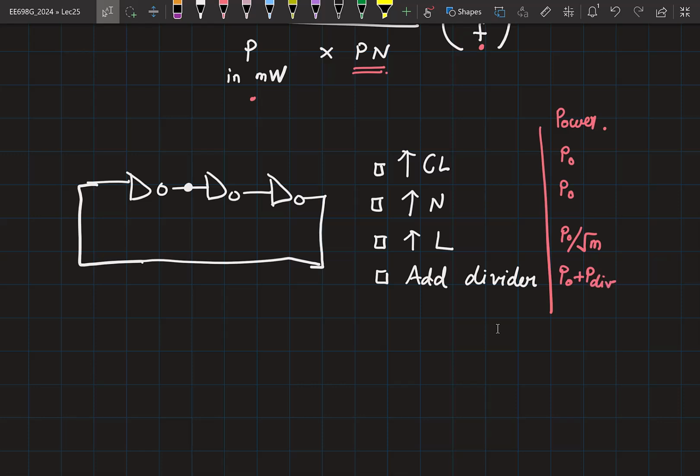Right? And now we have started comparing them based on the FOM. What did we find when you increase CL? What happens? You are adding additional capacitance, so you have both the expressions here. How do both of them change? Does S_phi white change if you add additional capacitance? No. What about S_phi flicker? Both of them do not change, right? Power is also not changing. Therefore, FOM remains the same.